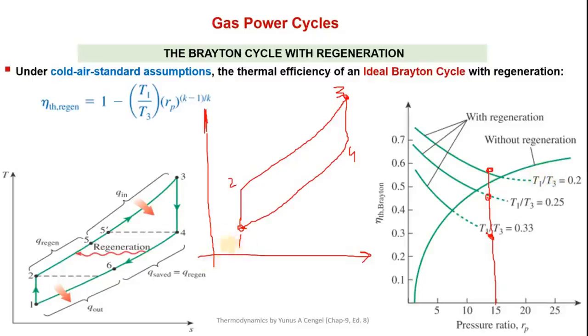air inlet temperature, which normally is fixed. The maximum possible T3 is about 1000 Kelvin. So let's try to understand by making T3 fixed at 1000 Kelvin. Now we can change T1. How can T1 by T3 be dropped?